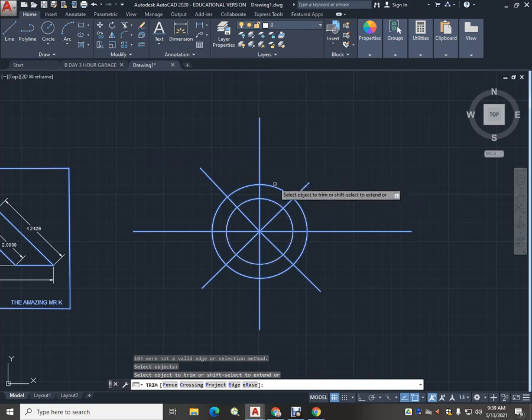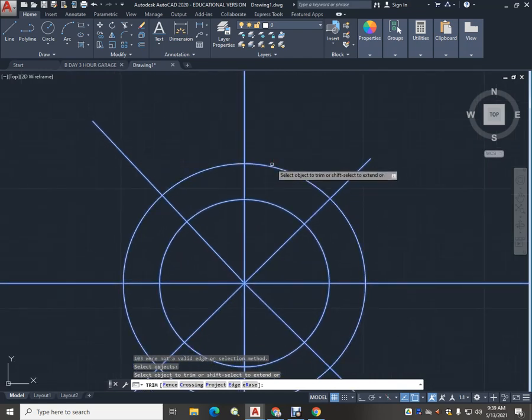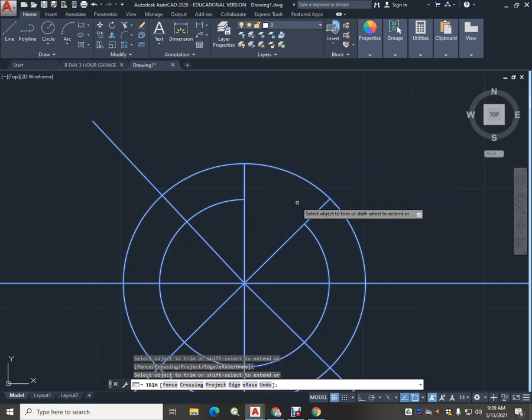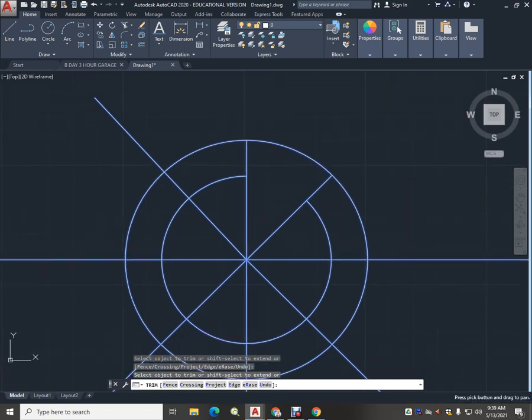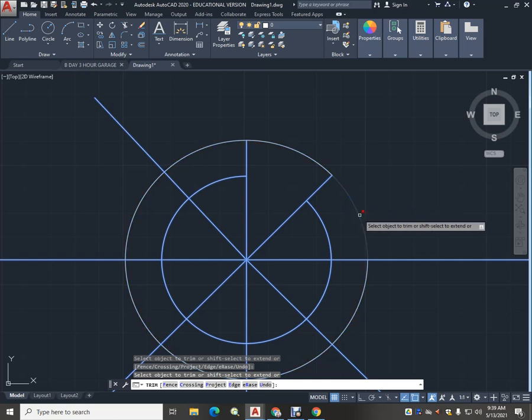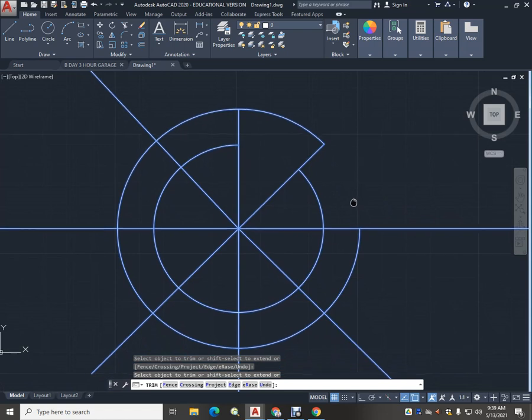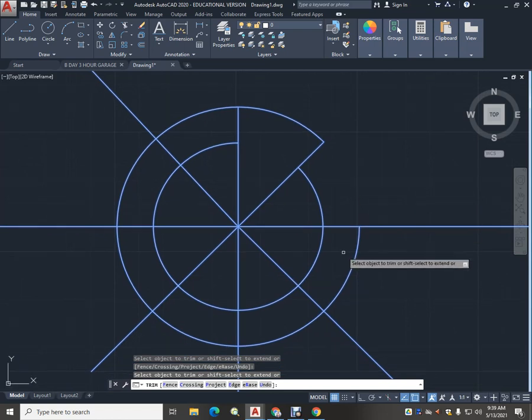So as I look at the drawing, I want to keep this one, but I want to trim that one out. So trim down to the part here. So now I have the long side. This one, I want to cut that out so I keep the short side. This one I want to keep the long side, so I'm going to take this one out.